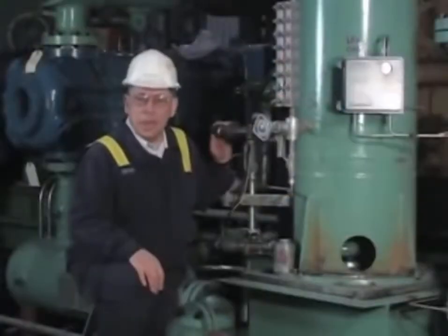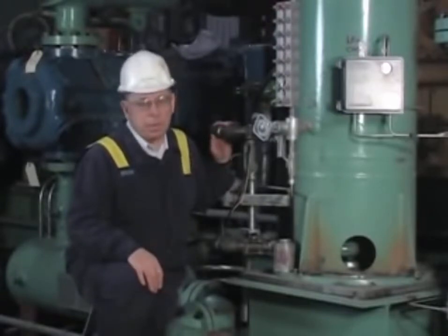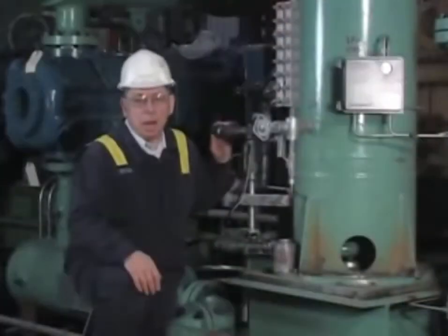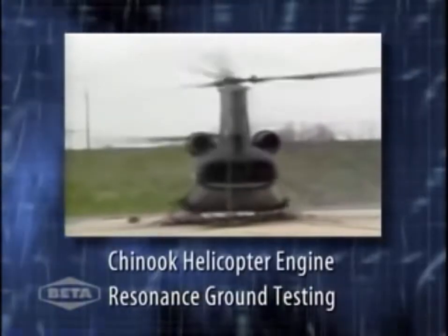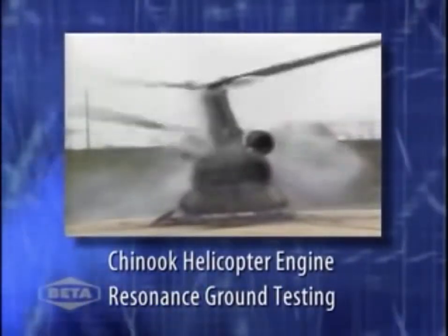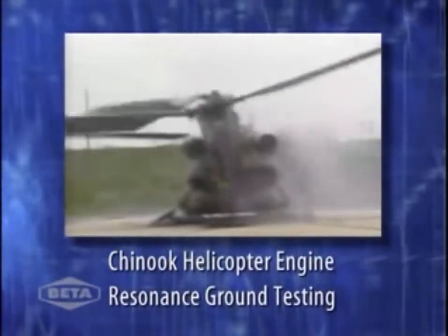In addition to the main piping and compressor components, we see a lot of vibration problems due to small diameter piping used for sight glasses, floats, thermowells, and other instrumentation lines. These lines can easily vibrate, crack, and even cause gas releases. Excessive vibration leads to high stress levels on machines and other related components, which leads to fatigue failure.